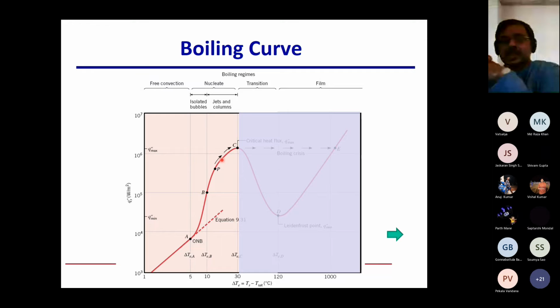Now, as this starts happening, we have what is called the formation of a film on the heated surface. It's a film of vapor, and remember, this vapor has low conductivity, and it is going to act as a barrier to heat transfer, because this vapor is now preventing the liquid from coming in contact with the hot surface. So therefore the boiling phenomenon is restricted.